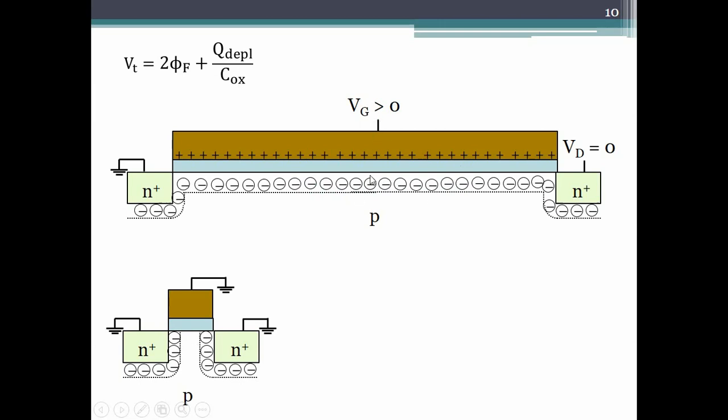And then some small gate voltage is applied, so there is a depletion region created here. In this, I have shown it without any gate voltage. Now what we see in this figure is that if we look near the surface, about 2/3 of the surface already has a depletion layer charge present.